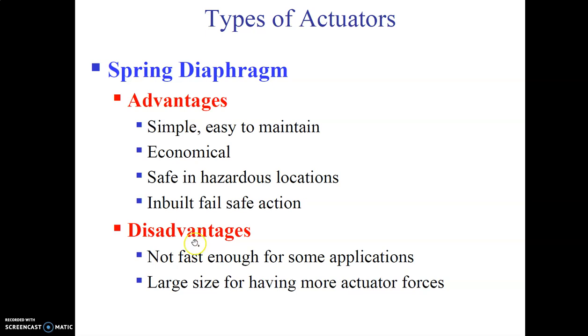Disadvantage is that the force that is generated is limited, so it doesn't give faster response. And in case if you want to have larger forces, then the size of the diaphragm goes on increasing.